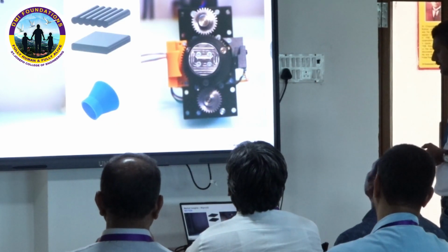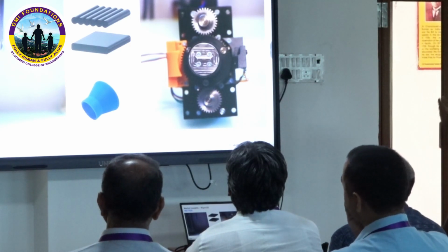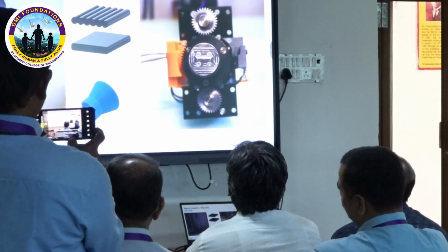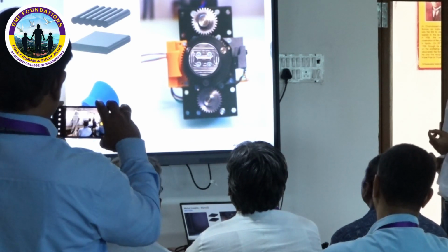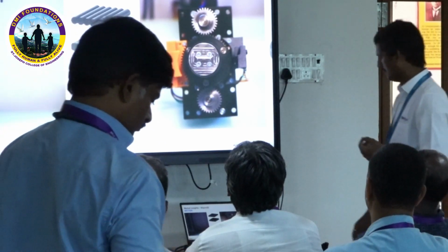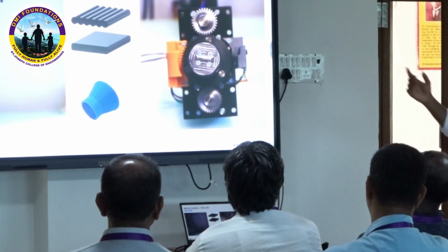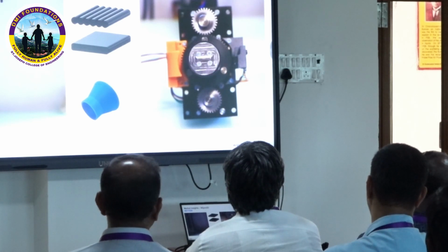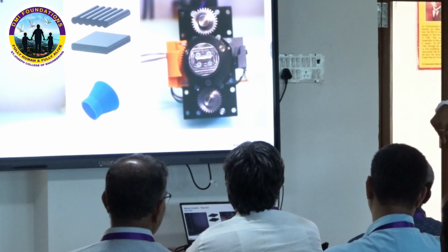And new innovations like the extruder. Currently it is giving one particular size of extrusion, right? It could be able to give different sizes of extrusion. Currently it is 0.4 mm. It is a static nozzle. So there can be innovations in the dynamic nozzle also. And omnidirectionality. You would have seen this particular technique in construction 3D printers. When there is a movement from right to left, like a 90-degree turn, the head is also going to rotate in one more direction. So you will get a better finish.